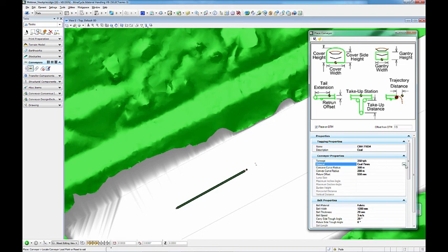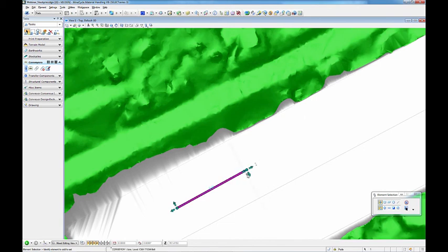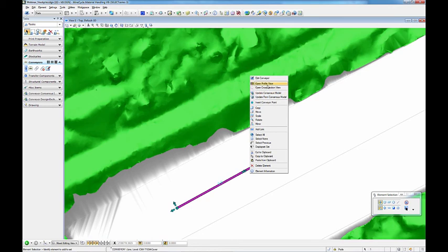Conveyor properties provide initial design criteria, such as a design capacity tonnage specified, and if a material is assigned, calculated information becomes available: burden height and maximum and minimum incline angles. Once the conveyor is placed, all horizontal and vertical lengths are also calculated. The conveyor can also be modified using graphical interactive manipulators.